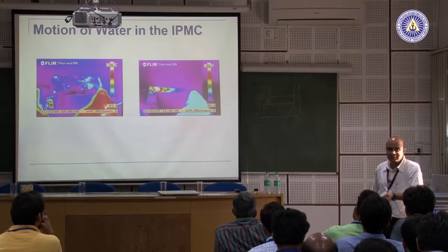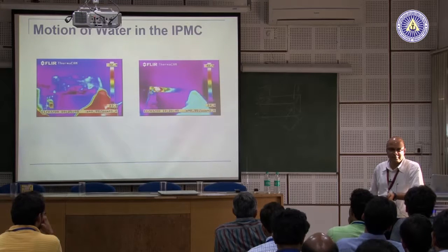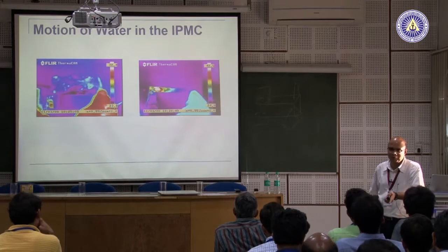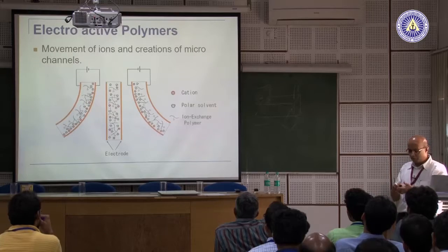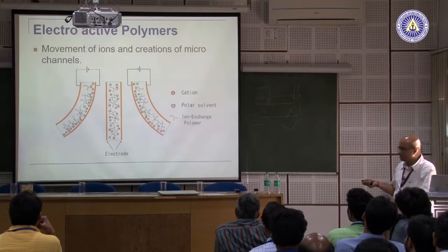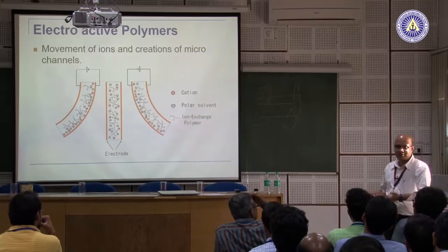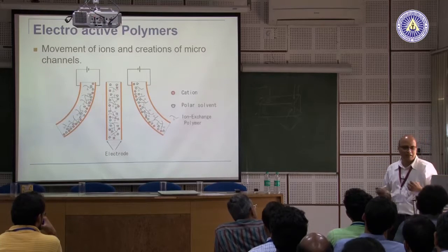Smart essentially means an actuator or a sensor which can behave like an actuator or sensor depending on how you want it. So, smart materials are those which can behave like an actuator or sensor at the same time. They are bidirectional. Say for example, if you give it a voltage, it is producing motion. If I give it a motion, it will produce voltage. A piezo is in a way smart. It can do both of them depending on how you are using it. There are many examples of this.